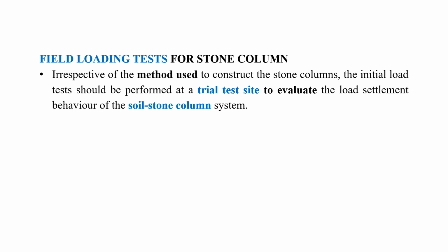So you can see here, irrespective of the method used to construct the stone column, the initial load test should be performed at a trial test site to evaluate the load settlement behavior of the soil stone column system. Wherever you are going to construct the stone column at this site, there we have to first go for the load test. How much load the stone column can take.